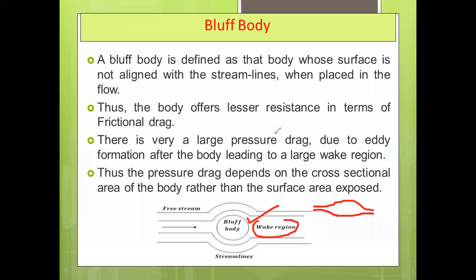And in case of this bluff body it offers a lesser resistance in terms of frictional drag. The viscous force resistance is very low. But there is a very large pressure drag due to the eddy formation after the body leading to the large wake region. In the wake region, large formation of eddies is going to occur there.